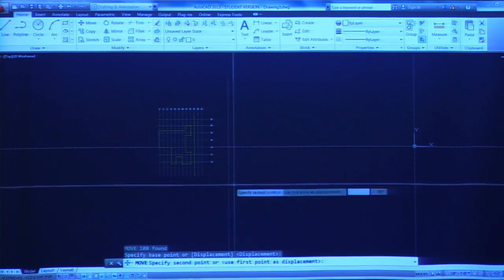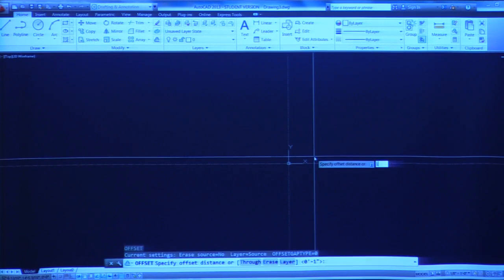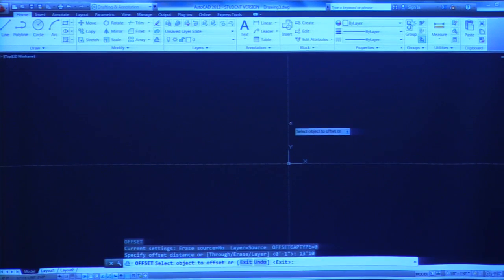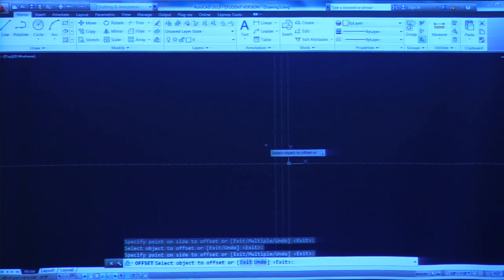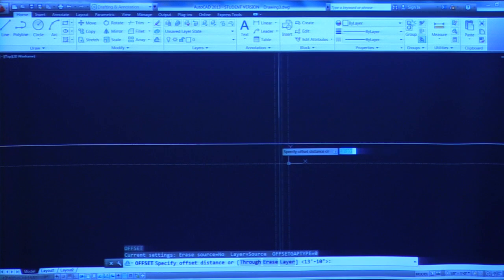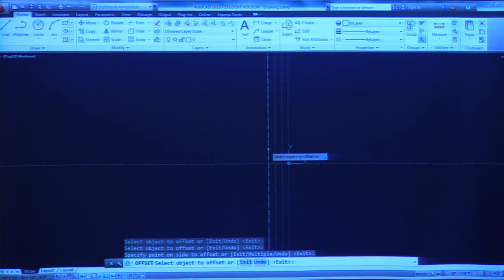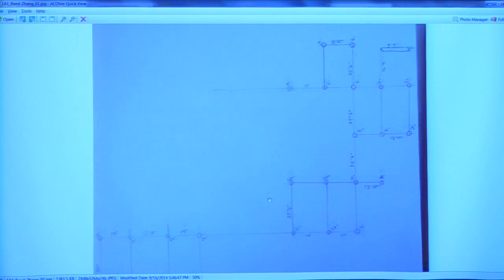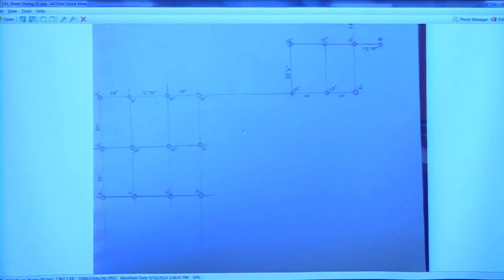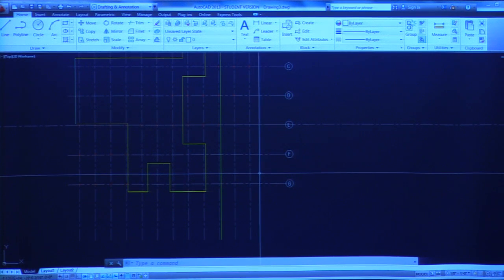I might move this even more, a full 250 feet. And I will offset 13 feet, 10 inches. Select that one, offset it again. And then, whoops, they're telling me 14 feet. So away I go again, offset 14 feet. Here we go, 1, 2. What else do we got? We've got a big space in here. I'm going to guess from prior knowledge, this is just me, that there are, oh, well, here's a good little clue. Here's a good little thing to do.